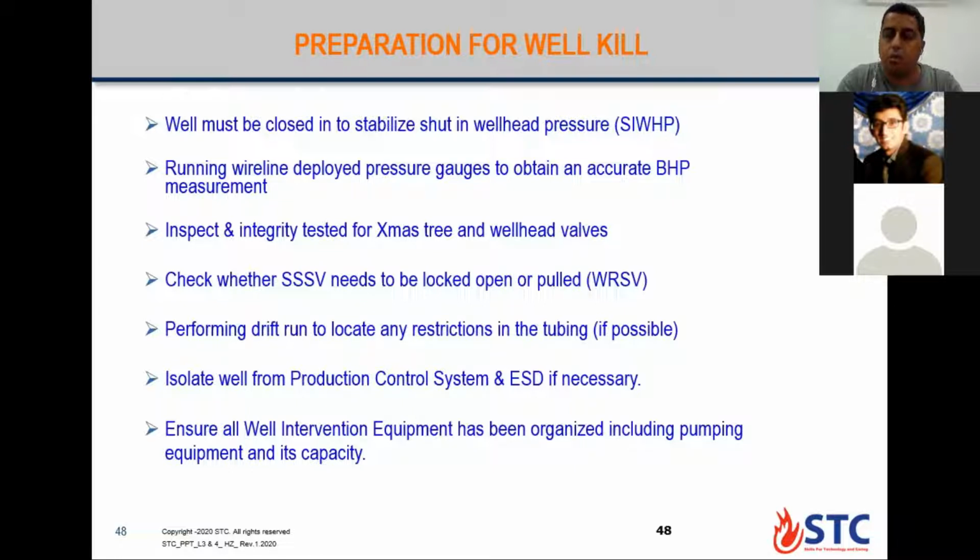Yeah, sure. If you have the lower master valve leaking, in this case you need to set one plug, like a back pressure valve or tubing plug, inside the tubing at shallow depths, plus you close the subsurface valve. So you now have two barriers, so you can replace the Christmas tree valves above.